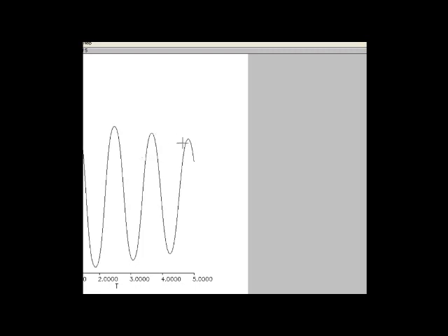Well, it's explained in the book that you just need to take more steps, because the backward Euler method, which is the only one that works for this differential algebraic system, has this tendency to die down, so it's just a question of increasing the number of steps. Again, you wouldn't know that, but it's all explained in the book. So let's increase the number of steps all the way to 100,000.